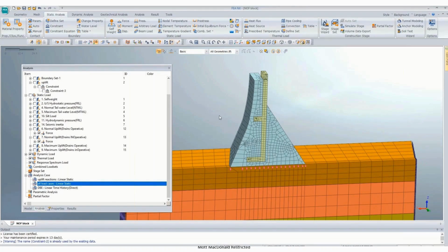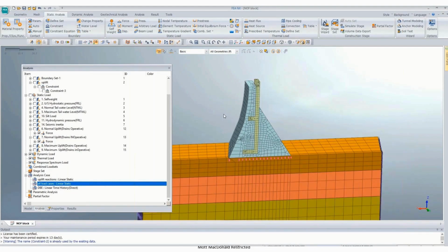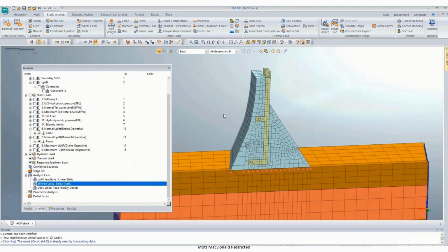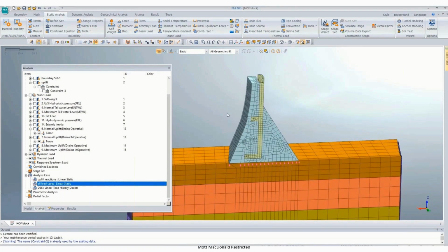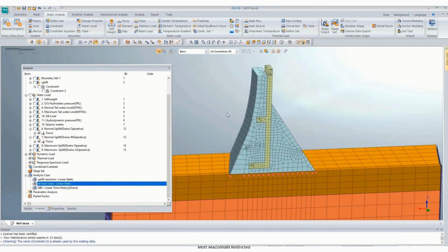Firstly, we'll be checking the stresses for load condition B, because that is a normal operating condition, and we have to make our dam safe for that. Then we'll be performing the stress analysis for load condition E, that is normal operation plus earthquake, and then load condition H, that is for MC condition, considering the provisions of engineering manual 6051.